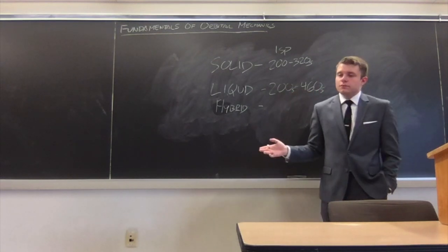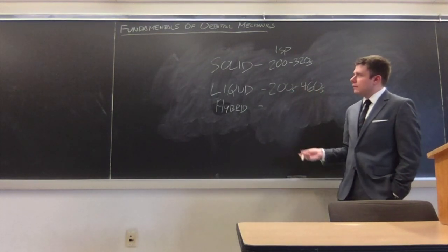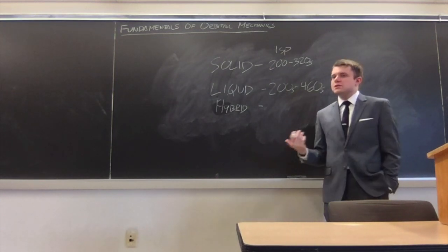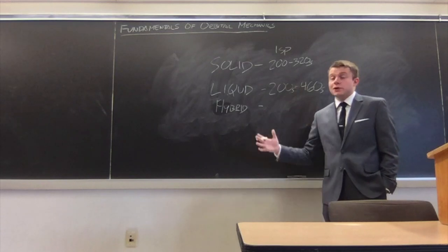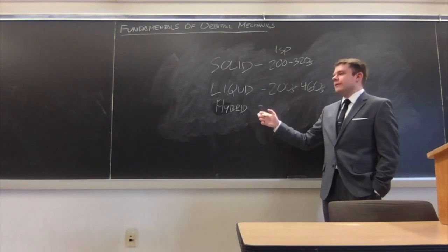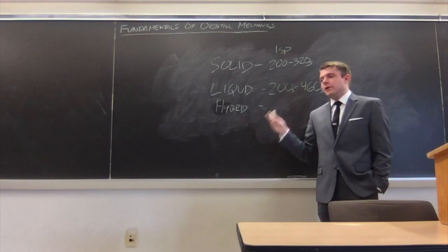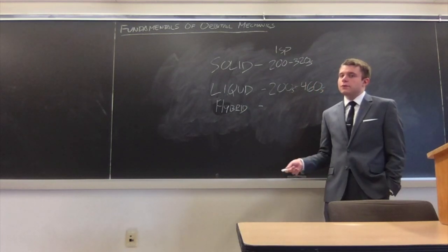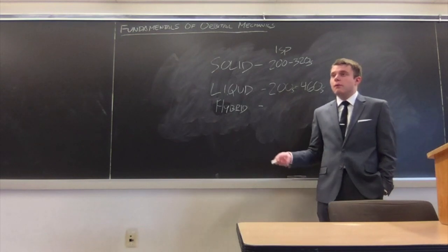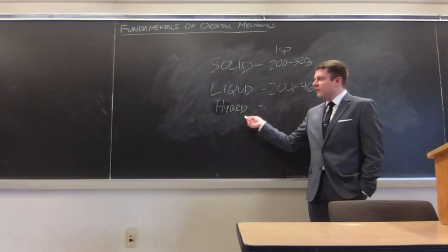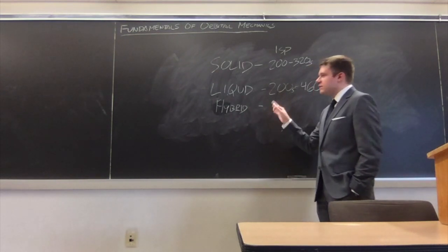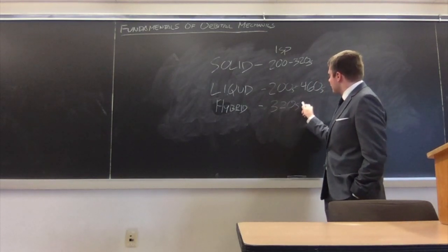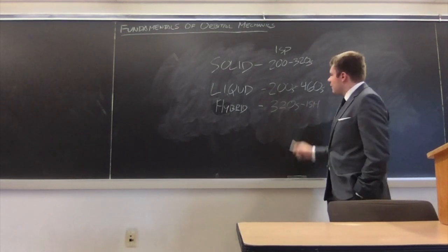And there's hybrid motors. Hybrid motors are kind of interesting because they're not really well classified in the world today. There are very few representations of hybrid rocket motors in general. Very few have flown on actual space flights. The only motor to actually do this is the one that's mounted to Virgin Galactic's SpaceShipTwo, which is previously Scaled Composites' SpaceShipOne's engine. Those are the only hybrid motors to reach space, and they have a specific impulse of, I believe, about 320 seconds-ish. They're not well quantified.